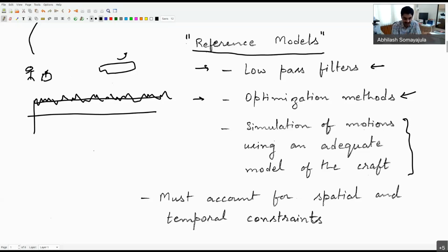So the so-called constraint here is not a typical spatial constraint. It's not that I can't actually go sideways. I can't go sideways instantaneously. So it's a spatio-temporal constraint which is coming into the picture. Okay. This particular constraint is actually a non-holonomic constraint. For those of you who were there in that tutorial organized by Oceans 2022, you must have seen this. This means that these can't be integrated to get a closed form expression. That's what it means. But it's not of relevance to us, so don't worry if you don't understand what that holonomic term means right now.